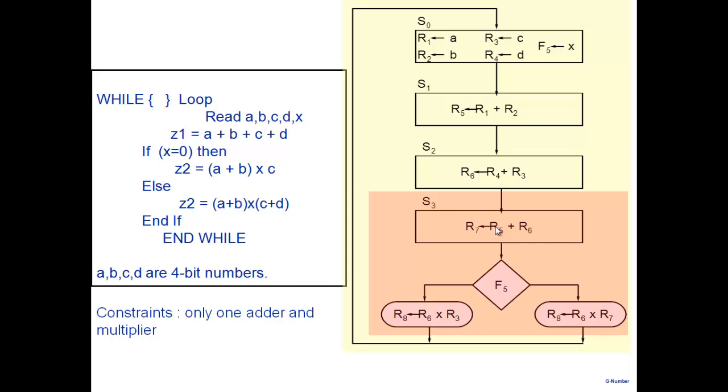Some statements occur anyway the moment you enter the state. So some control signals are generated to cause this to happen, and then depending on this condition, either this occurs or this occurs. So again, my controller would be going from S0, S1, S2, S3, these states here. And now we are modeling the controller as a Mealy FSM, and depending on the condition, there would be different control signals generated for the data path.